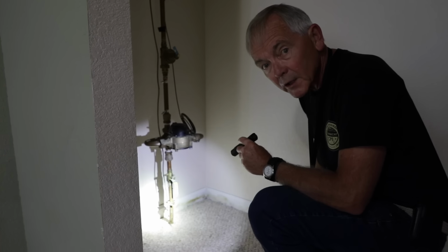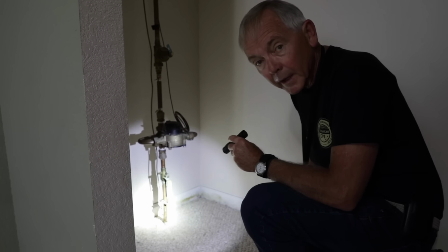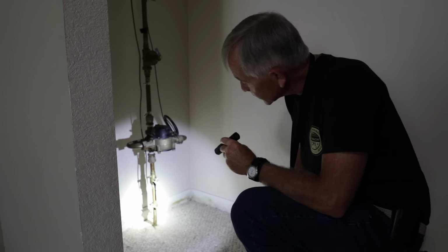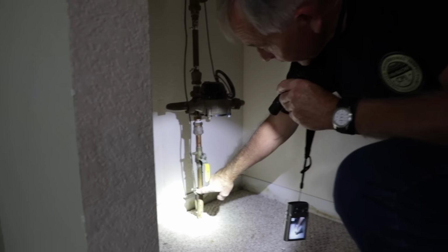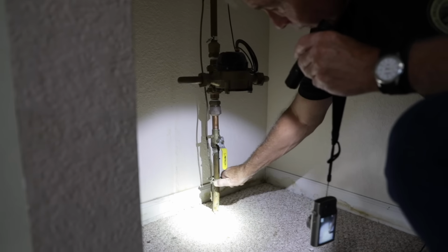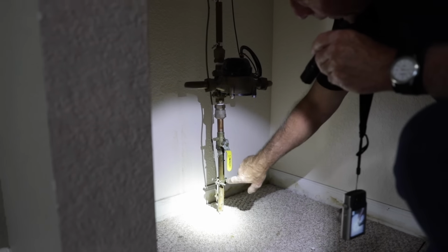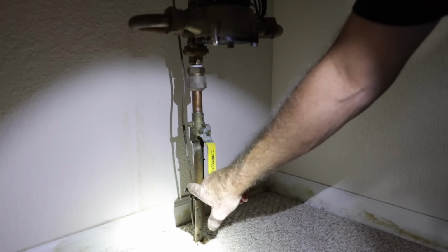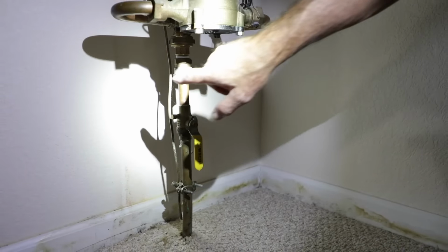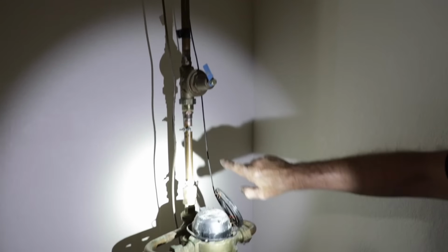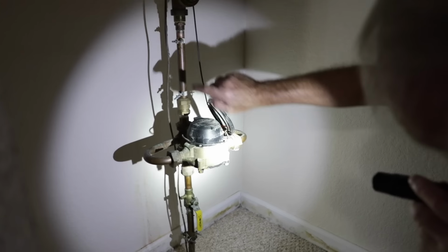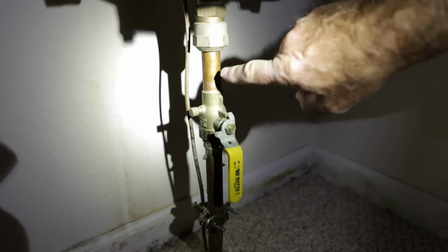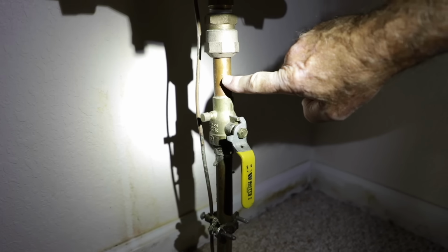Okay, we're now in the basement of the home, and I wanted to come down here and check the other grounding connection point on the water main coming into the house. I can see our clamp right here, so I'm just going to make sure that that's tight. This is a copper water main line. Here's my grounding electrode wire back here, and as I'm coming up to look at that, I've noticed that there's no bonding jumper around the water meter itself. I'm going to take a photo of this and mention this in my report.